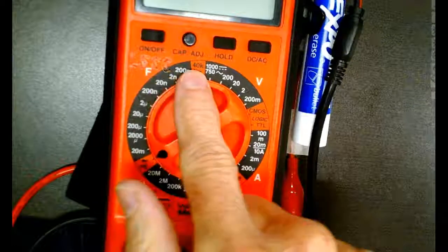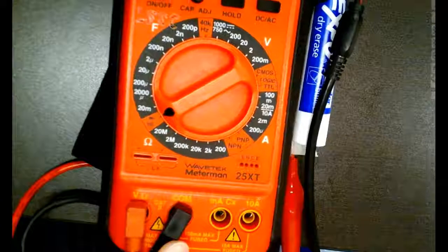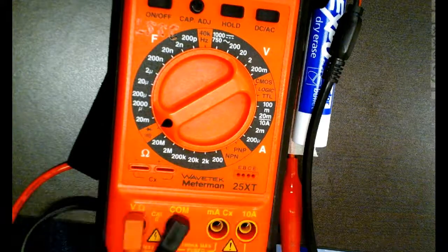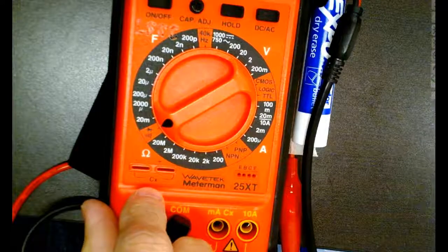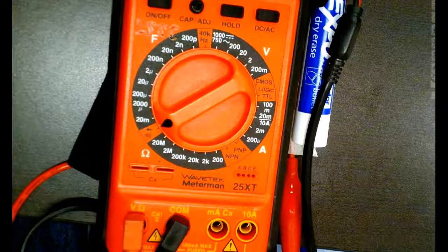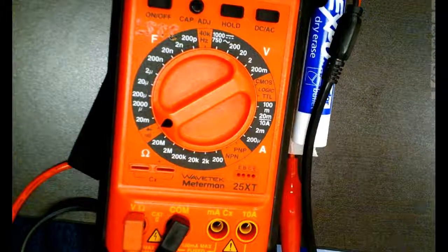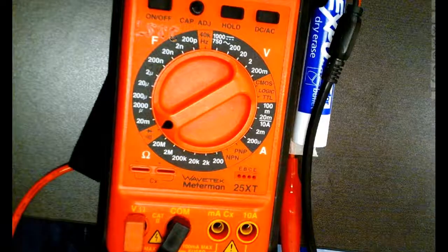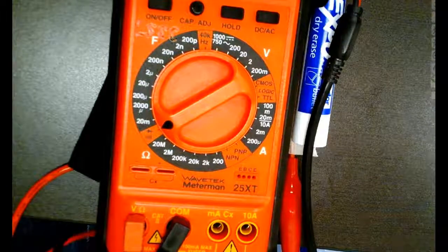So this has got a function generator and it actually measures frequency. And then it's got a capacitance scale on here somewhere, because here's where we hook the capacitor, right here, C. So this generates an AC wave when you hook it up there, because you can't measure it without AC. If I took a capacitor and put it across my ohm meter, it's going to measure an open, unless it's a big capacitor, and you'll actually see the plates charge up. But a small capacitor charges so fast.